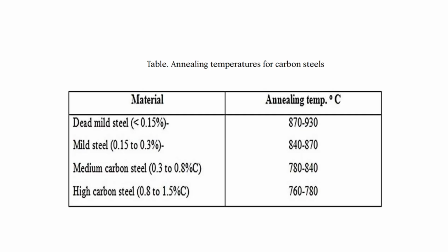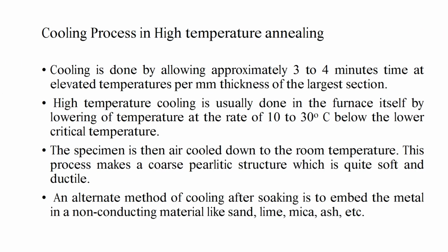Mild steel, 0.15 to 0.3%, 840 to 870. Medium carbon steel, 0.3 to 0.8%, 760 to 840. High carbon steel, 0.8 to 1.5%, 760 to 780.